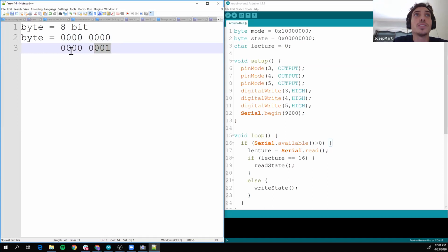Last year, in my ukulele, I had four LEDs on each of the frets because I have 4 strings. And then here I define the mode and also which fret. So I modeled a communication protocol that with 1 byte sends everything: if I want to write, if I want to read, which fret and which string. Making a codified communication was much better, because you avoid a lot of problems.